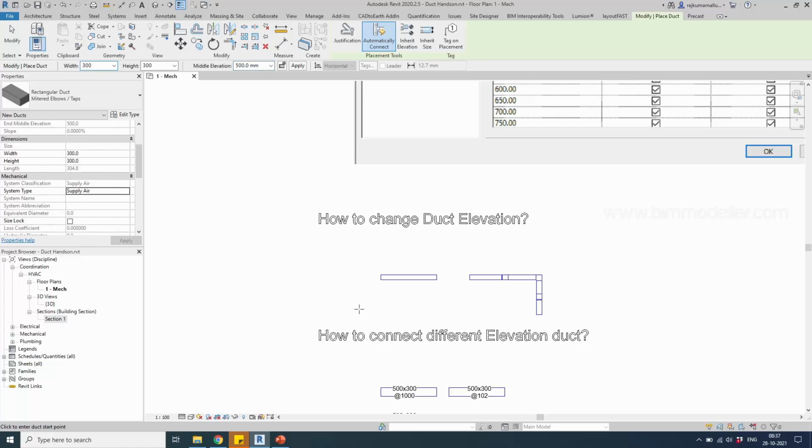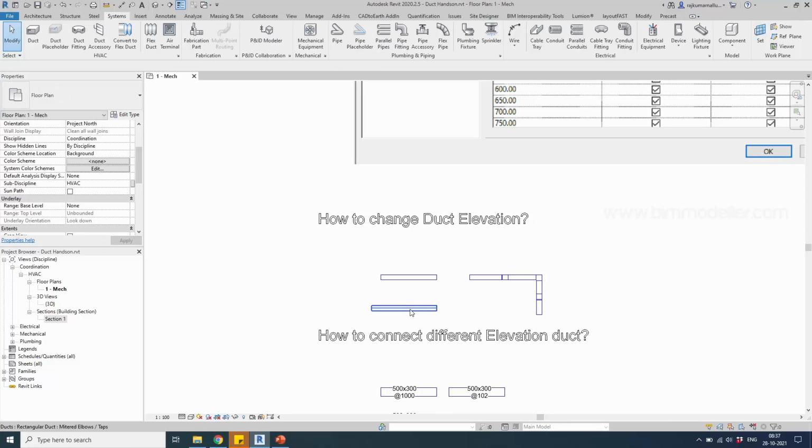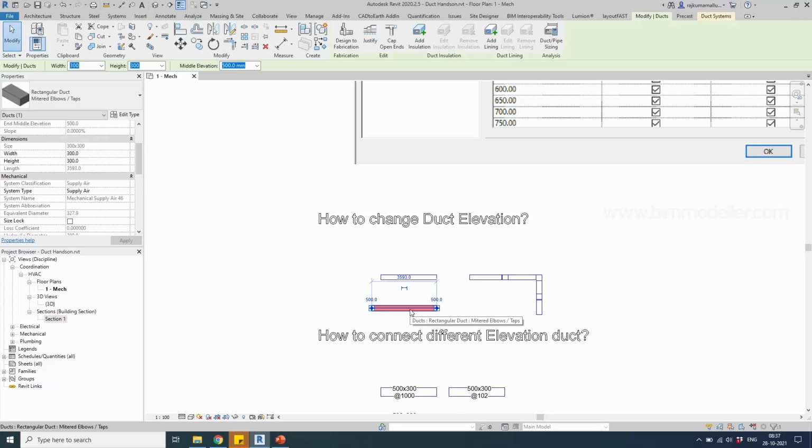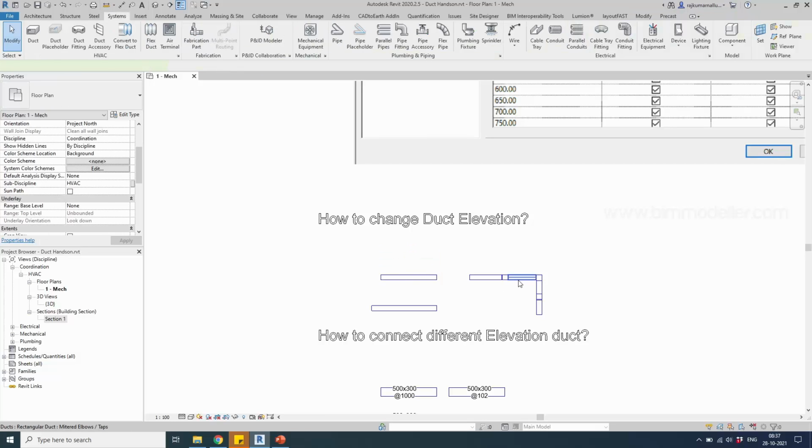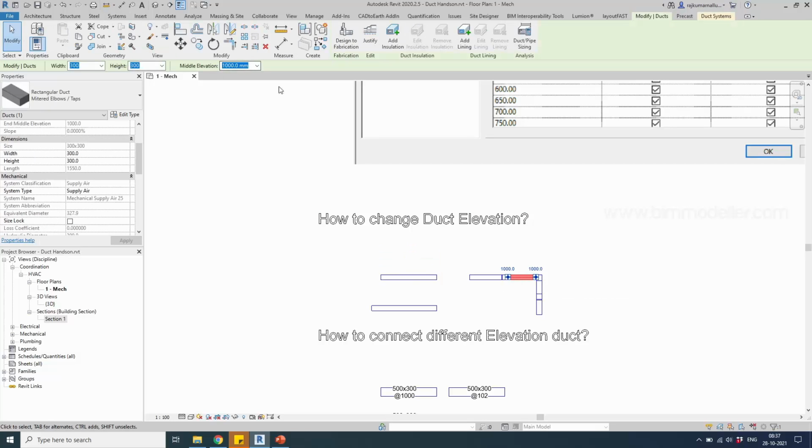You can go ahead and create the duct at 500. So the elevation from the level will be 500. You can select them and see that. The previous duct will be around 1 or 1.6. If you select the other elements, you will see their heights also.